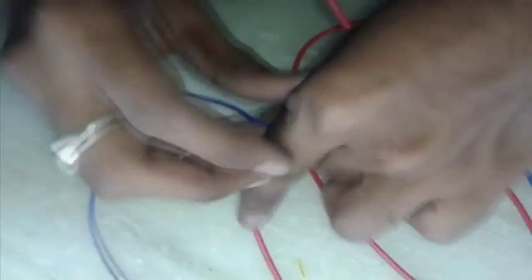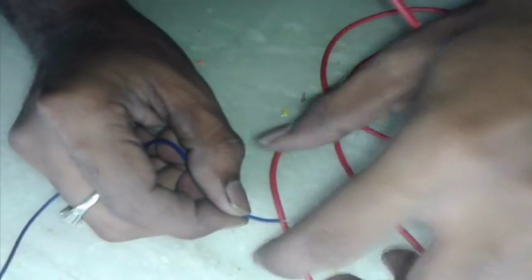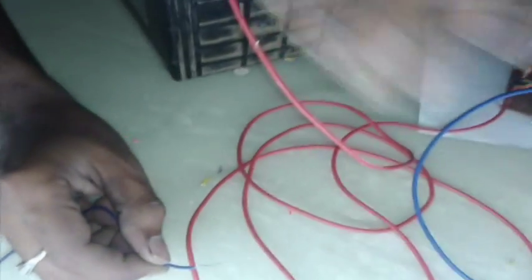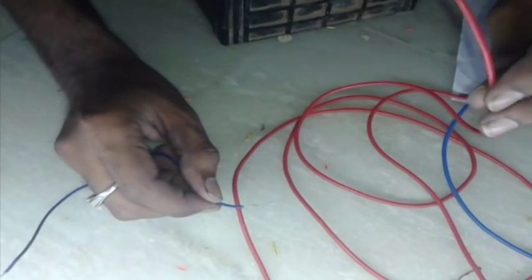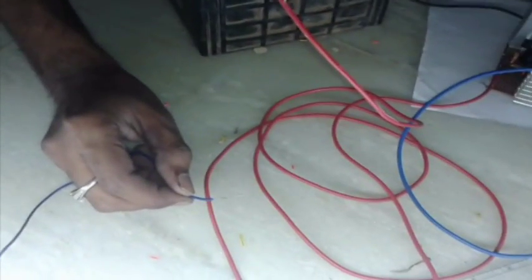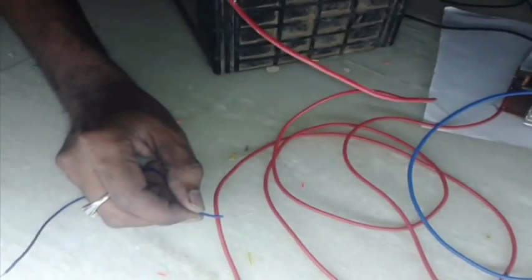It's soldered. If you see this side, this is a single lead wire. They could not tolerate the heat coming from the battery, and the wires also got overheated, so we could not get proper output. If you use a multi-lead wire of 1.5 square mm thickness, you can get better output. You can get the very best output when you use 2 square mm wires, which are generally used for household wiring purposes.